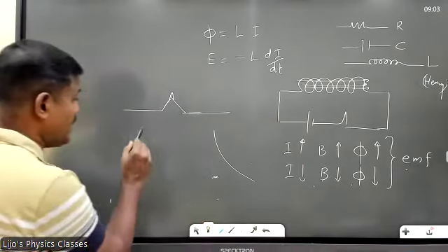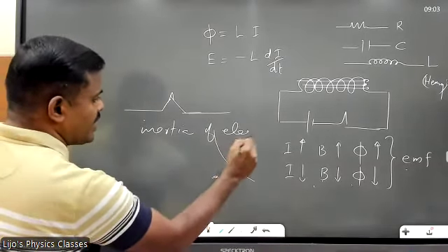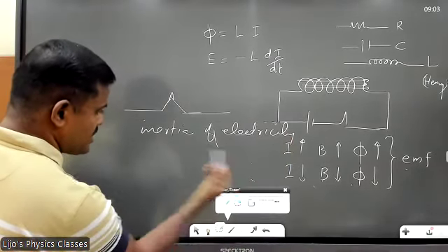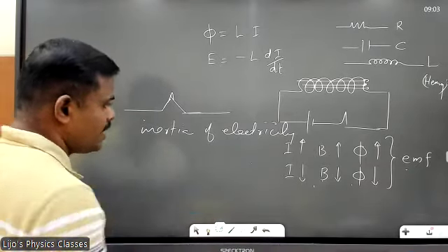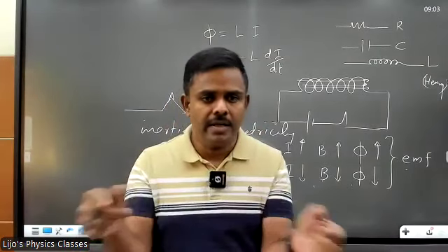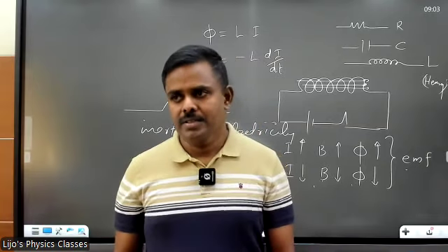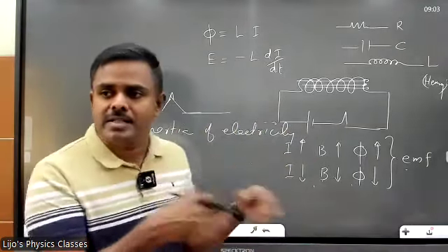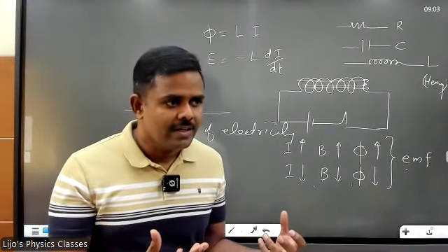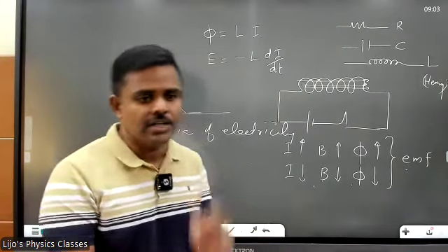Self-induction is also called inertia. I didn't tell you yesterday, I was about to tell you today. Inertia of electricity. Inertia means laziness, in a common man's language. When you are trying to switch it off, it is lazy to be switched off. Imagine you are switching it off. It is resisting, right? It doesn't want to be switched off. Lenz's law opposes it. When you try to switch it on, again that is opposed. That is why it is called inertia of electricity.